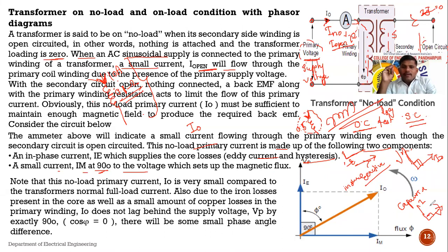Okay, see, due to this winding it is not wholly reactive, or this current taken from the supply is not totally reactive. So no load current taken from the supply it is not exactly lag 90 degree behind by voltage. व्होल्टेजच्या एक्झॅक्टली 90 डिग्रीने तो लॅग होत नाही, but it will lag somewhat less angle than 90 degree. 90 डिग्री पेक्षा काहीतरी कमी अँगलने तो लॅग होईल. Right. So all of you understood this point? लक्षात आला का हा पॉइंट?